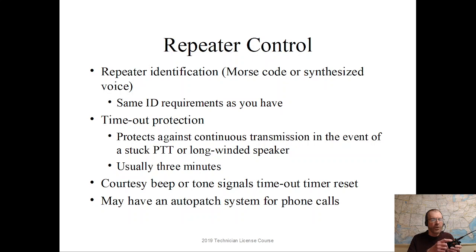So this thing could be transmitting if we sit on it, or if it gets jostled, and something is pushing against it, and the transmission is going on and on and on, and it can be tying up a repeater. So repeaters have timeout protection against that, which protects against a continuous transmission in the event of a stuck push-to-talk switch.